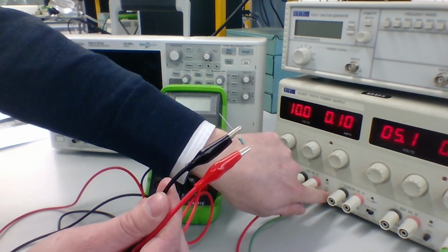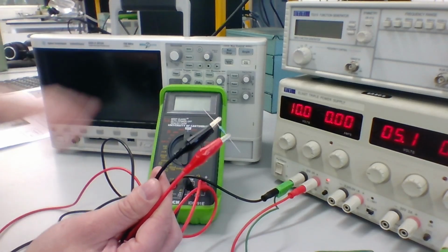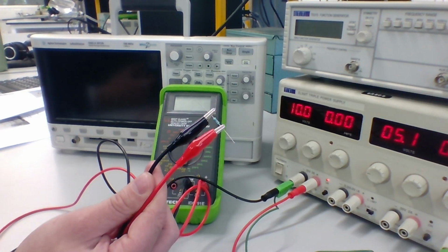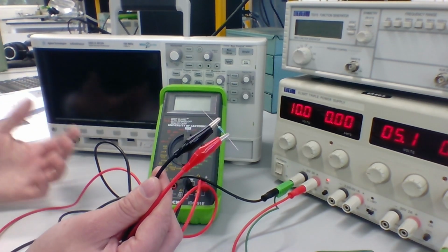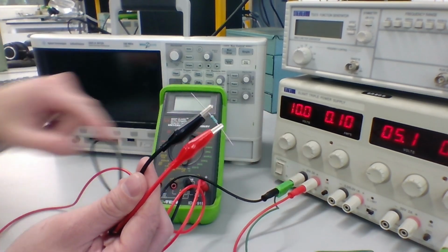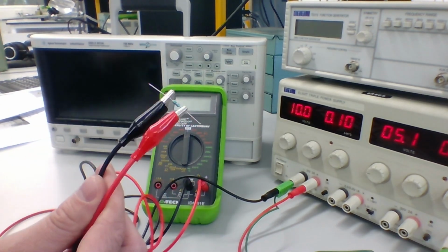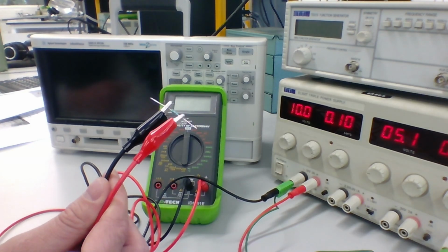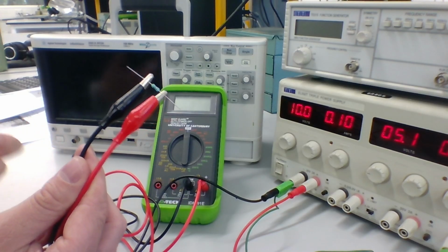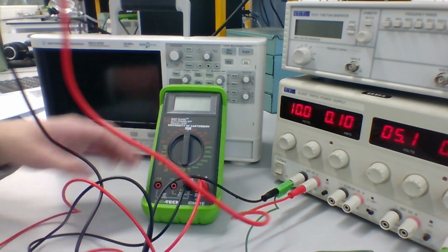If I turn the power supply on, current will flow through the resistor. Nothing has gone wrong, as we expect. Our voltage is set correctly. Our current limit will prevent anything bad from happening. But we don't know what's actually happening. We have no measurement here. So I'm going to turn the output off. Again, I generally recommend turning the output off when you go to change your probing setup of a circuit. If you're just moving a probe from one point to another, you can usually leave the circuit on, but if you're changing a bunch of connections, just turn the power supply off. It's just a bit safer.